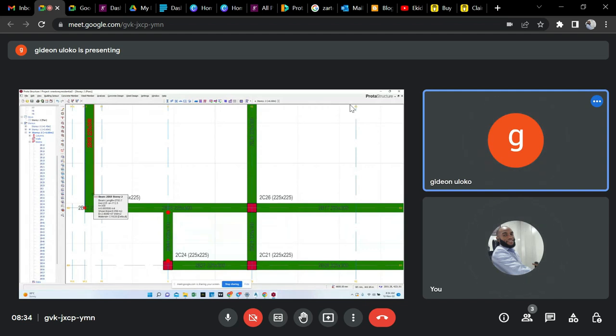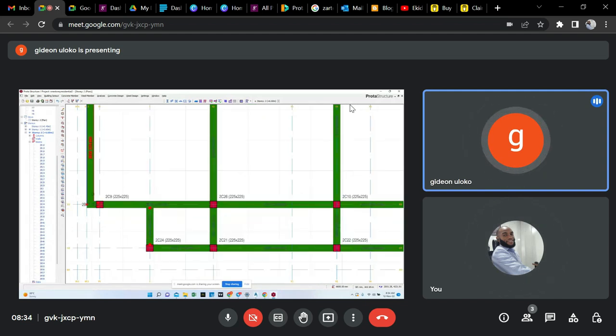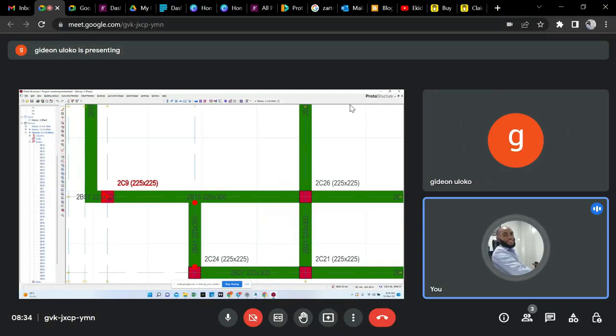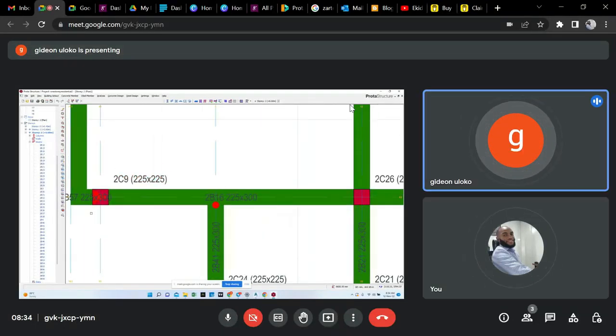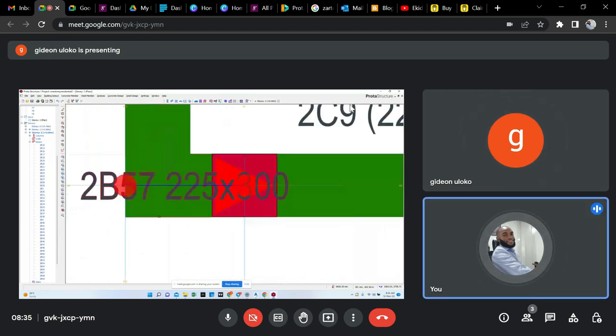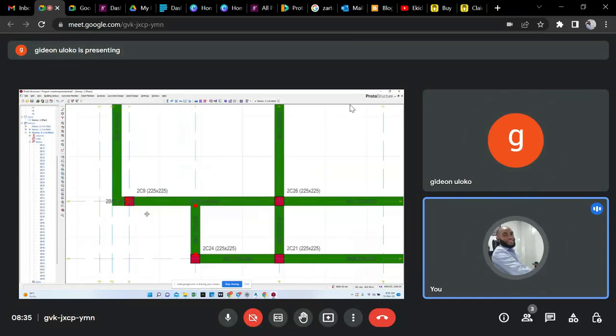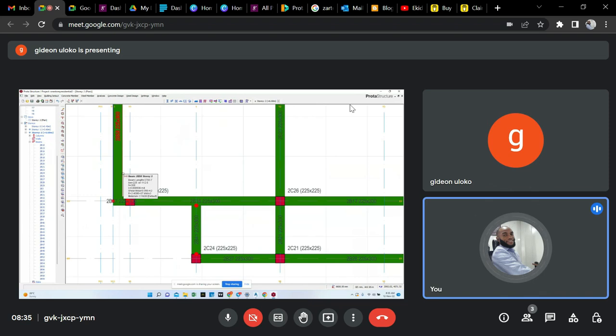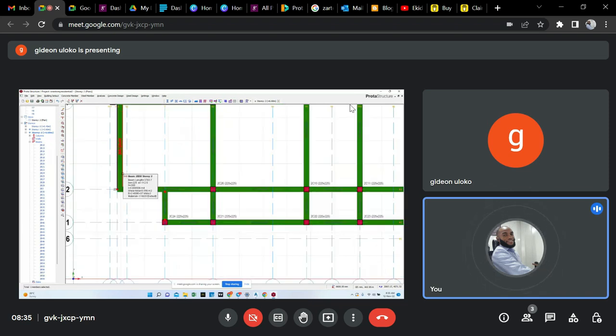So one will hinge the one that's resting on this beam. Yes, there's a small beam here. No, that's a cantilever. Don't hinge it, but hinge the vertical one resting on it. Yes, that one should be hinged. Also, that side of the building too should be hinged, because they're like twins.